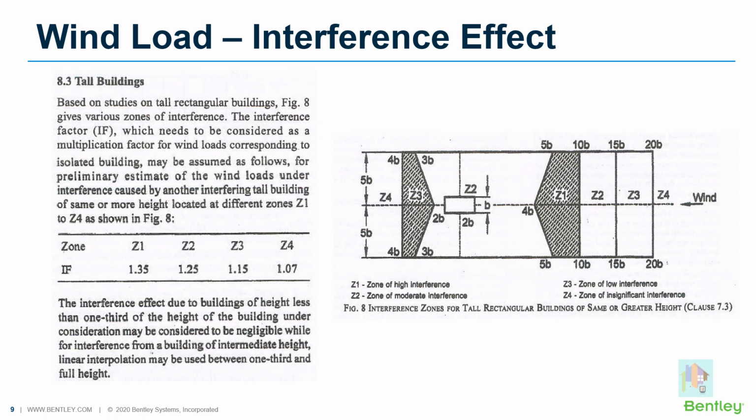For any tall structure, you need to find out the interference of wind due to the presence of other building structures located in the catchment area or the nearby zone. Depending on the dimension of the building, the interference area is determined, and further, depending on the height of other buildings, the interference factor is computed, which determines the final wind load intensity value on the tall structure.